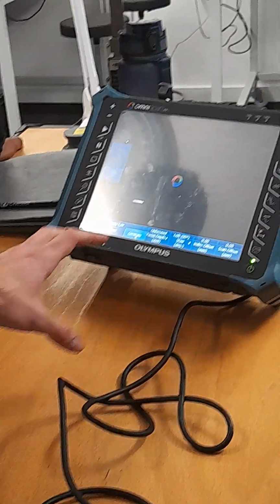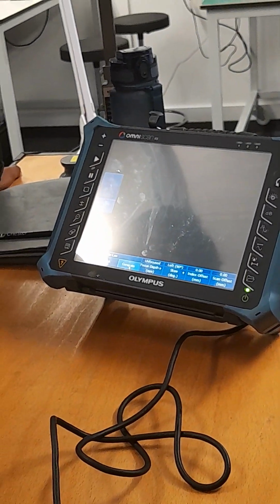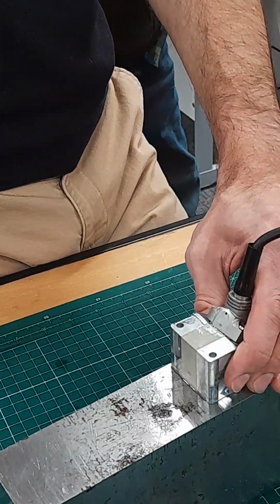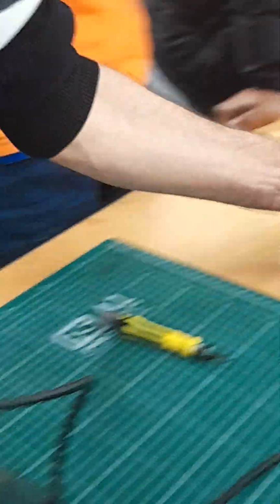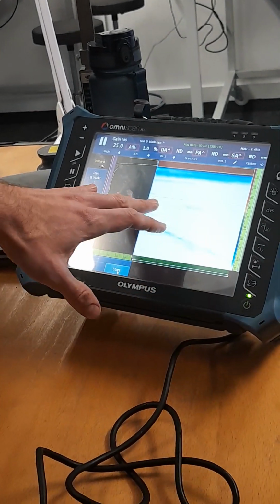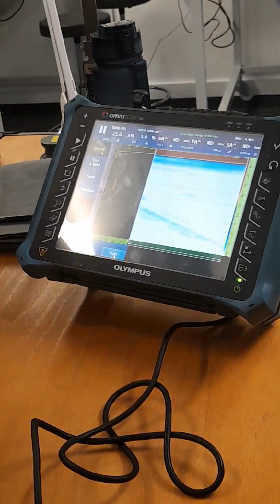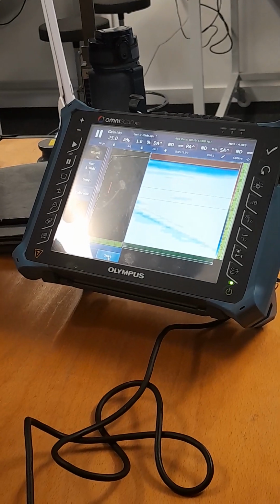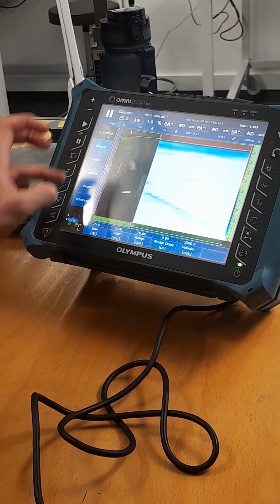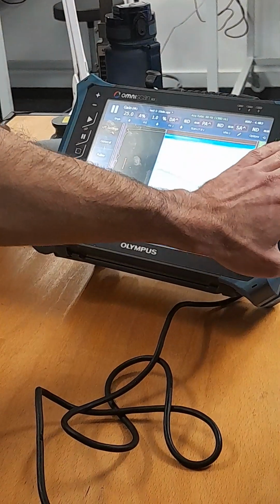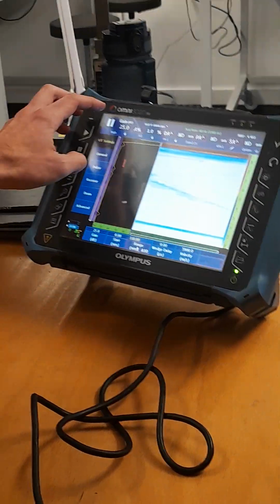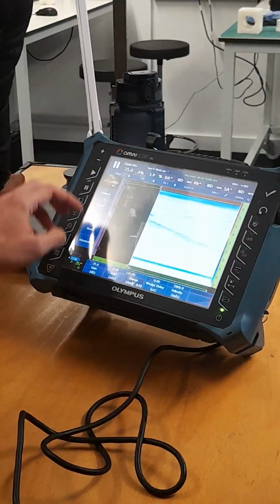So now it's generating the beam. So here, hopefully, if I was looking deep enough, this is looking down to 70 millimeters depth. That's why I see nothing. It doesn't reach, my screen doesn't reach the bottom. So if I go to UT settings, that range, we start seeing the bottom. Let's leave it at 100.